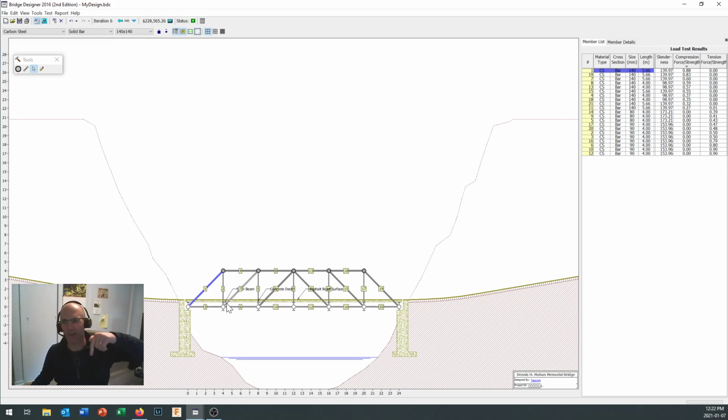That is going to have a vertical component and a horizontal component. So we've been talking about component vectors in some of our other lectures. Well, that's why, because when you picture this vertical force applied right here, okay, this is now pushing down this way with a vertical component pushing down on this node and a horizontal component pushing horizontally on this node. And of course, if it's pushing downwards here and backwards, this node must be pushing upwards and over on the top. And then this one's pulling down right here.